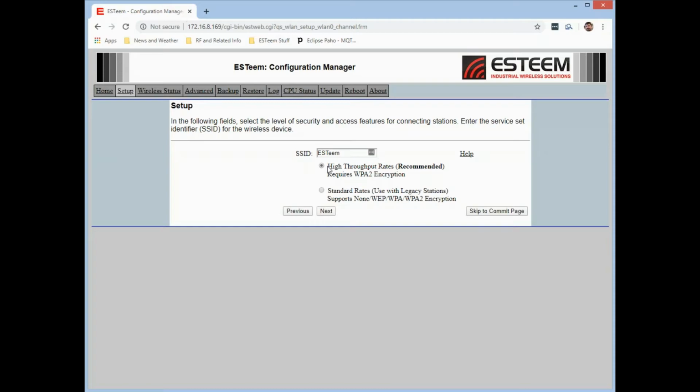If you're not really certain where to start, especially on these unlicensed frequencies, a good place to start is in the middle. Check to see if it's operating the way you want it to, and if it isn't, then move off to a different channel. That is the beauty of these unlicensed frequencies, that you can move around within them, and there really are no ramifications to it.